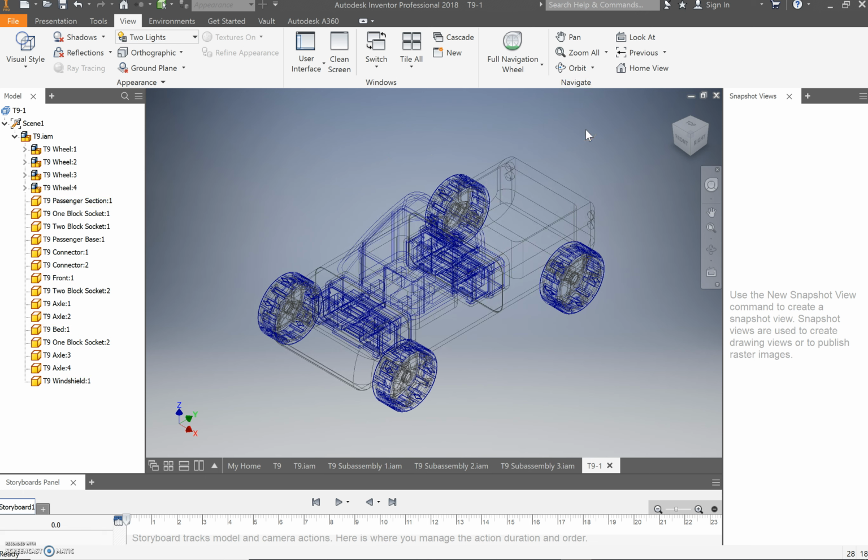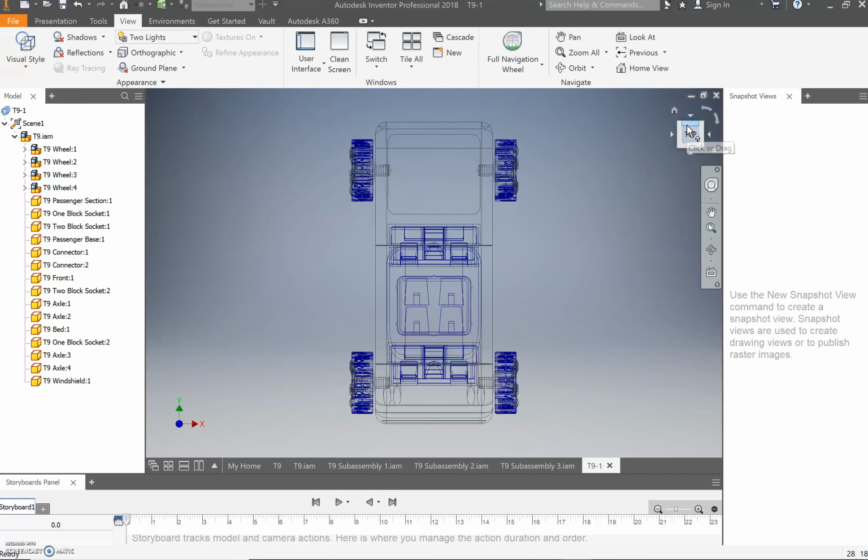So the first thing I wanted to do is tweak components, and I wanted to do that on the first sub-assembly that we did. I'm going to do that by keeping all of our components together and moving them at once. That allows us to not have to move all the different components numerous times. So to do that, I want to make sure I have the right wheel selected. So I want that wheel there, and then I want that wheel there. Some of you guys may have the different parts of the wheel selected in there, so you might need to do that. So I went ahead and did that there.